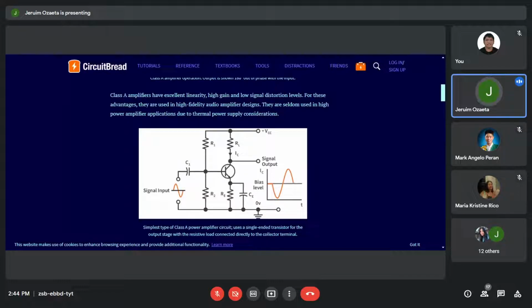But there is the presence of capacitor C sub 1, and this C sub 1 will delay the positive-going input current. Why is it going to delay? Because the capacitor first needs to charge, and the charging current of the capacitor first has to increase the voltage, and the current will lag. Therefore, the charging of the capacitor will be delayed.